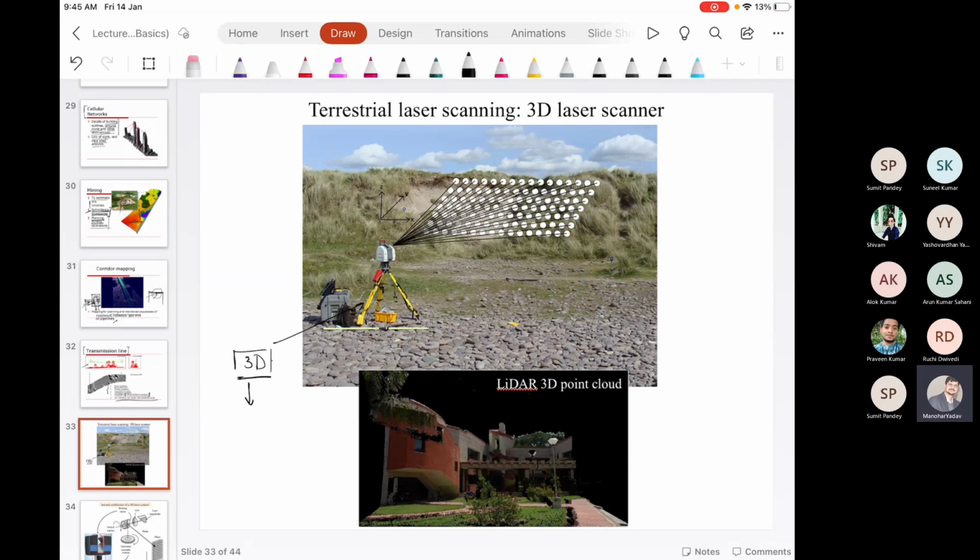A 3D laser scanner means it computes the range from the transmitter aperture, and the angle alpha from the vertical axis, the z axis, and beta from either the x or y axis. So there are angle encoders. Angle encoders calculate two angles, and there is a receiver, transmitter, and counter circuit. Using these components, the range is calculated.